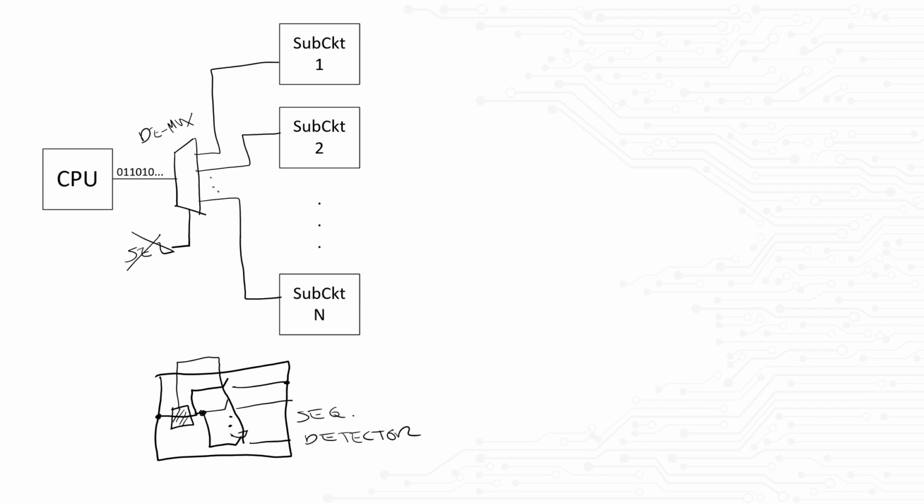There are many ways to approach the process of building an FSM, especially if you have plenty of experience. However, we at Hardware Ninja like the following approach. You can tell the interviewer, let me write the input sequence to be detected. To this, let me add 2 random bits to the start and end of the sequence, like so. If this is my input stream, then the output of my sequence detector will be the following.